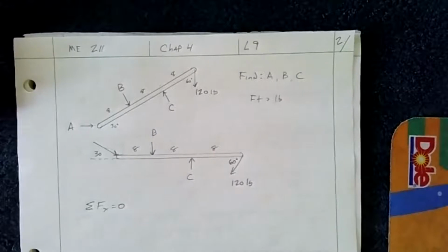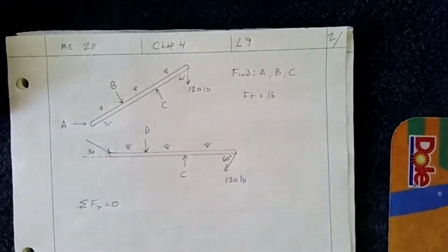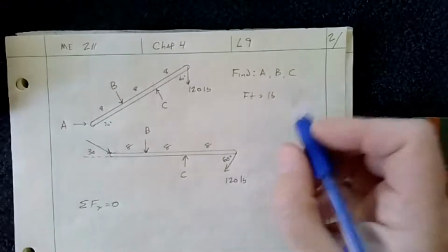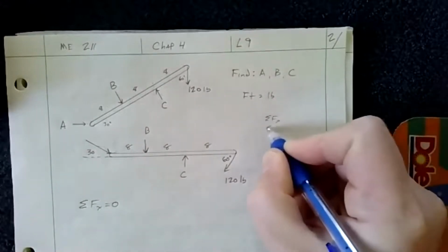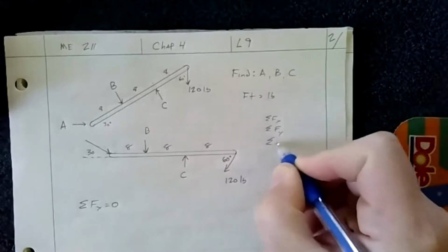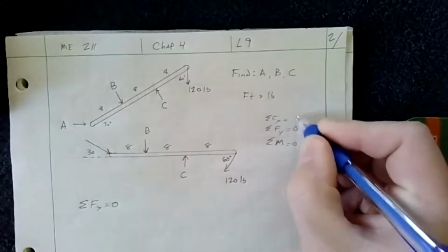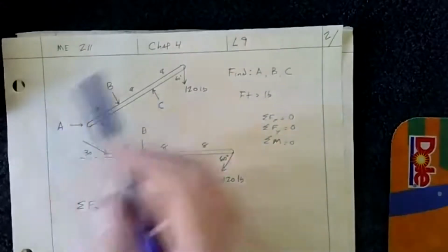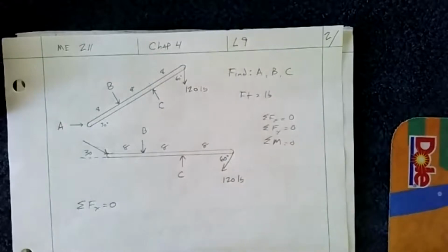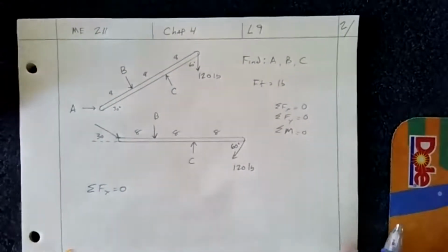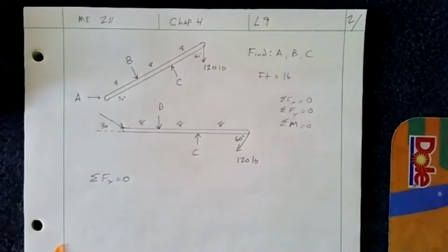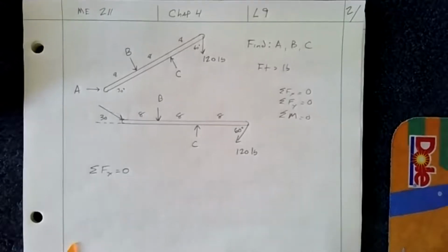All right. Now, in all the problems we do, and I'm speaking of 2D, we really only have 3 equations. We have sum the forces in the X, sum the forces in the Y, or sum the moments about a point. And that's it. That's all we have. 0, 0, 0. So we have 3 equations in this case, so we have 3 unknowns. And that's how we're able to solve it. So we'll never give you a problem that's statically indeterminate. There are ways to solve statically indeterminate problems, but just not in this class. That's something you'll deal with if and when you take CE 204.